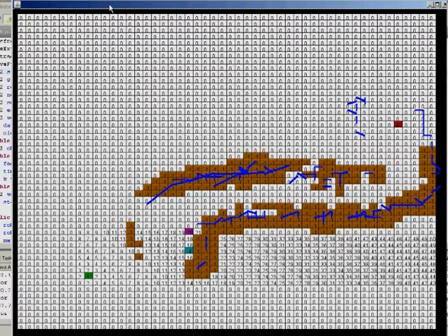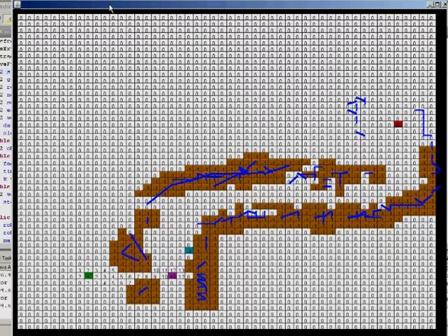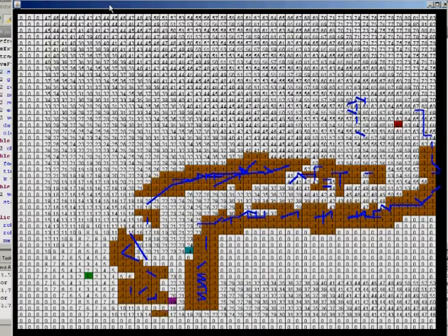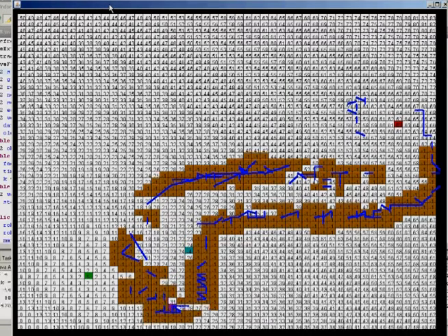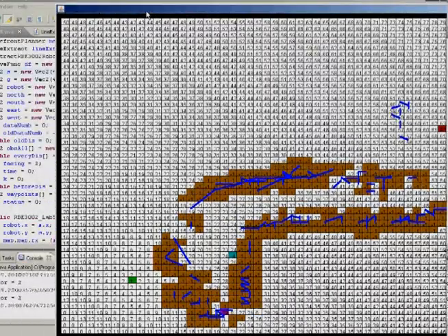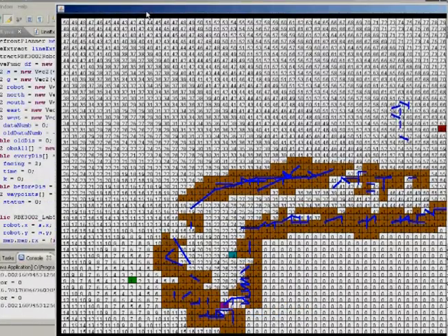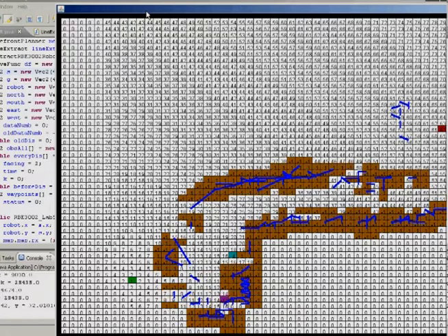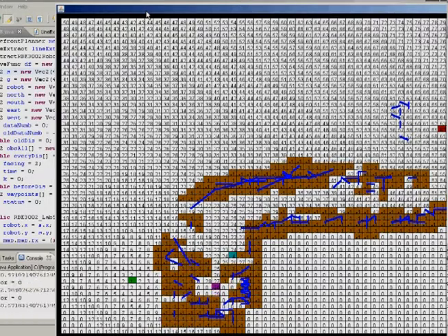We also have what is called an escape function. When it gets blocked off, when it realizes there's some obstacle blocking the path, for example because our line mapping blocked off all the paths and it can't go anywhere, it gets stuck in the same position in a forever loop, then it's going to use one of the escape functions.